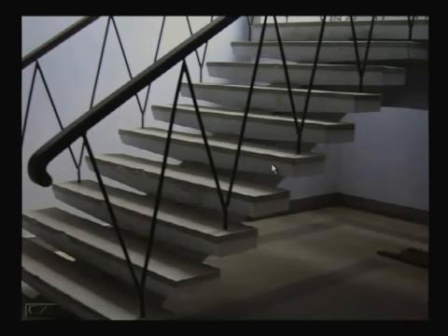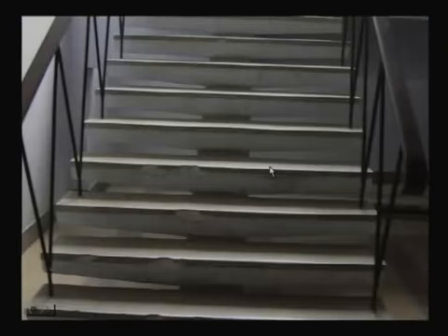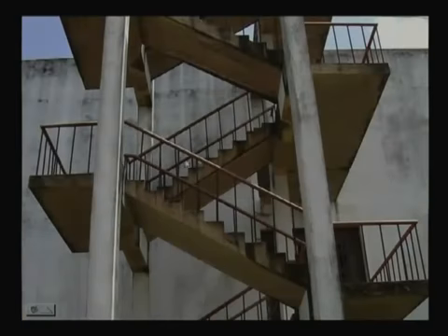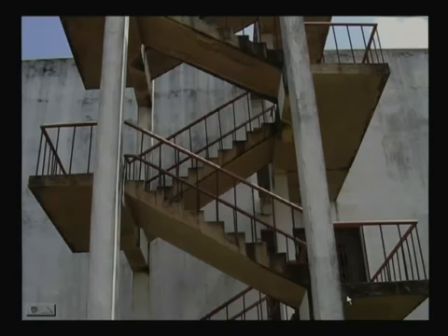So that way you can design, but the most popular one is this, another view of it. In most cases you will find this type of staircase. This is the most popular one, and we shall design this one. But I shall also tell you how to design other staircases. For any staircase, you have to find out the governing bending moment, how it is acting, about which axis, and then design accordingly, as well as for shear force.